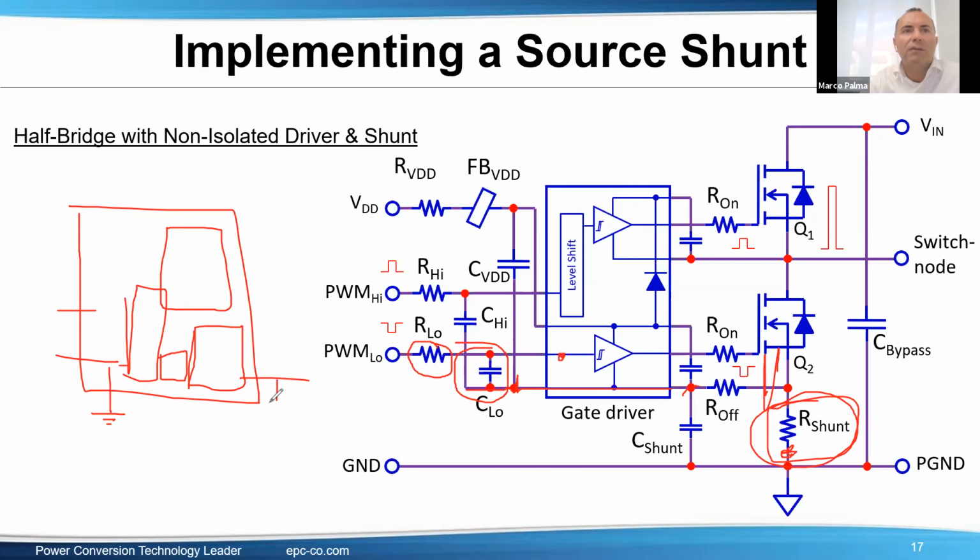So you have two different grounds, and this one you don't connect to the power ground. It's just the return of your GaN FET, and then you can put whatever you want here, as long as this gate driver can withstand the imbalance, and usually the imbalance is plus minus 5 volts, so it's okay, then you don't have a problem.